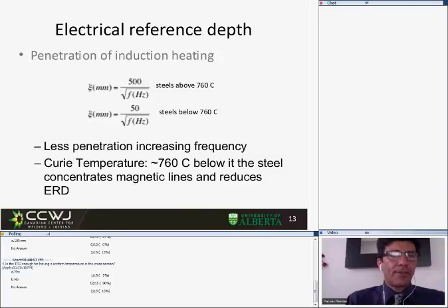So it's very difficult to get penetration. This issue of self-shielding, that is called the skin effect, is magnified by the magnetic properties of iron. Something interesting about iron is that it's magnetic up to more or less 760 degrees C. I'm giving you a sharp number.